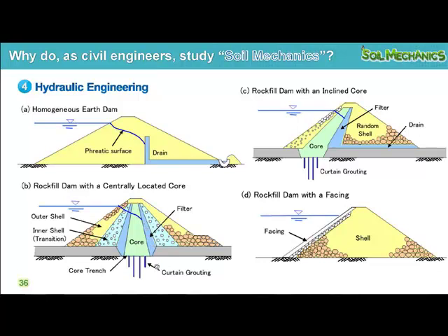The surface of the dam can be rock riprap protected by granular material, and this we call the core that allows water to flow through it very slowly. And this can be a filter layer or drain layer that can drain water flow to here.